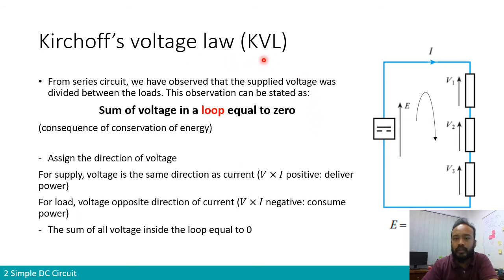Just now it was Kirchhoff's current law, coming from the fact that in a parallel circuit your current is divided into the branches. Now we're going to look at the other one, which is related to the series circuit, Kirchhoff's voltage law. In Kirchhoff's voltage law, our circuit is in a series configuration. We have our EMF supply coming from a DC supply over here, and then we have 3 resistances, for example, and across all the resistances we can find the potential difference.